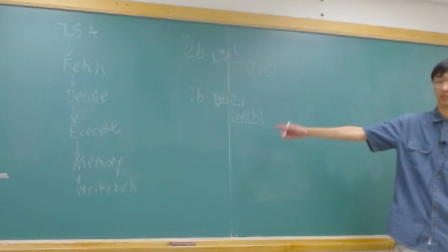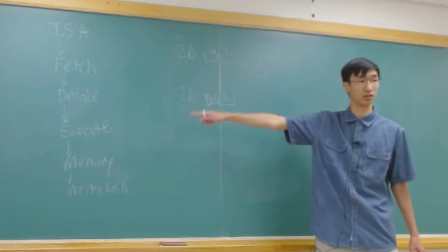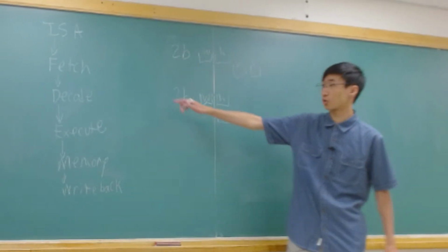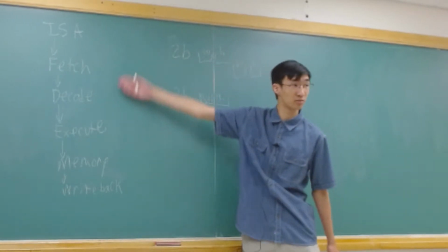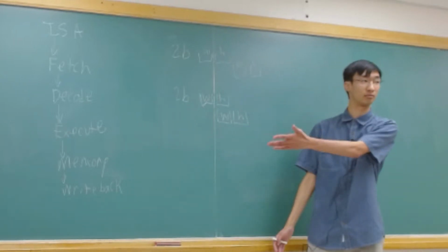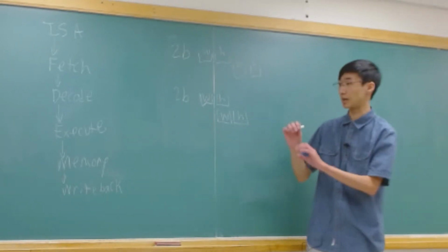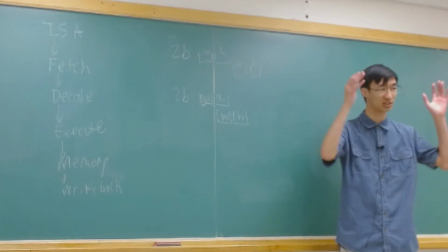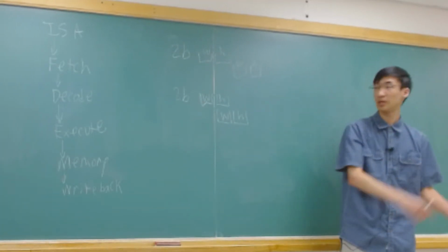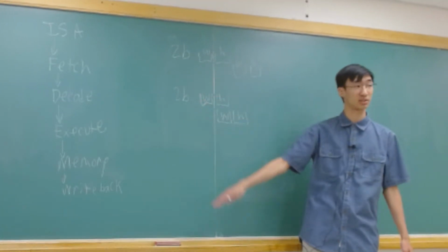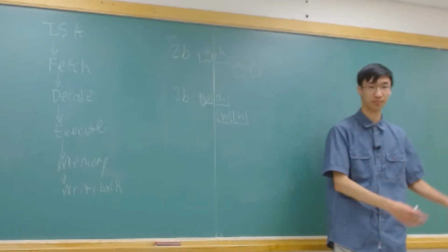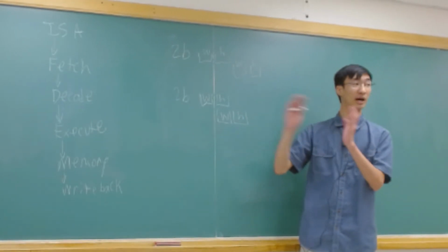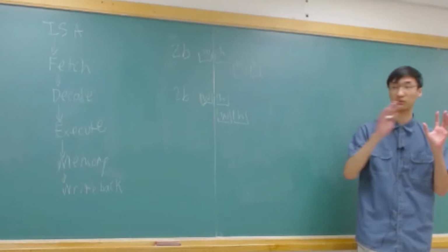The CPU is pipelined. That's why we have different stages here. Because if you let the instruction run all the way through to the end, all of this circuitry is just waiting. It's doing nothing, right? So we actually do some extra work to figure out how to break them apart and lockstep them to doing specific pieces in steps so that we can feed more instructions through with higher throughput. And so this is what throughput means.